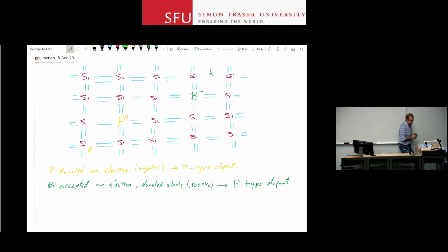And let's say if I want to reduce the resistivity of this piece of silicon, I can add as much phosphorus as needed. By increasing the number of free electrons, I drop the resistance. I could do the same thing with boron, right? So I could add enough boron there so that I have so many holes that will meet the requirement for the electrical resistivity. I shouldn't do both at the same time.